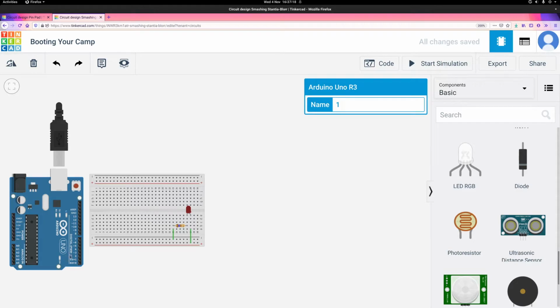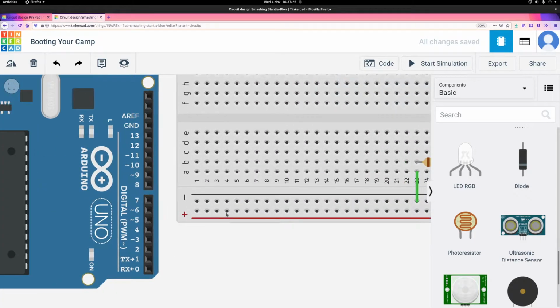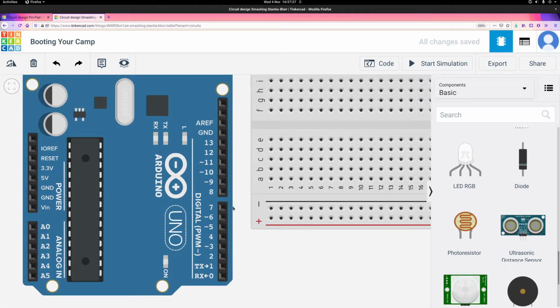So you can tell they're digital pins because it's labeled here on the Arduino. It says digital. And if it's a bit difficult to read this bit, well, actually I can zoom in, don't I? I don't need to tell you. There you are. So it says digital here. All of these pins are digital pins, which means they can either be 1 or 0, so only one of two values. And 1 means there's a positive voltage there, so that would be equivalent of like our 5-volt. And 0 means they're at the ground state, or there's no voltage there, so that would be the low state. So we'll see how that works in just a second.